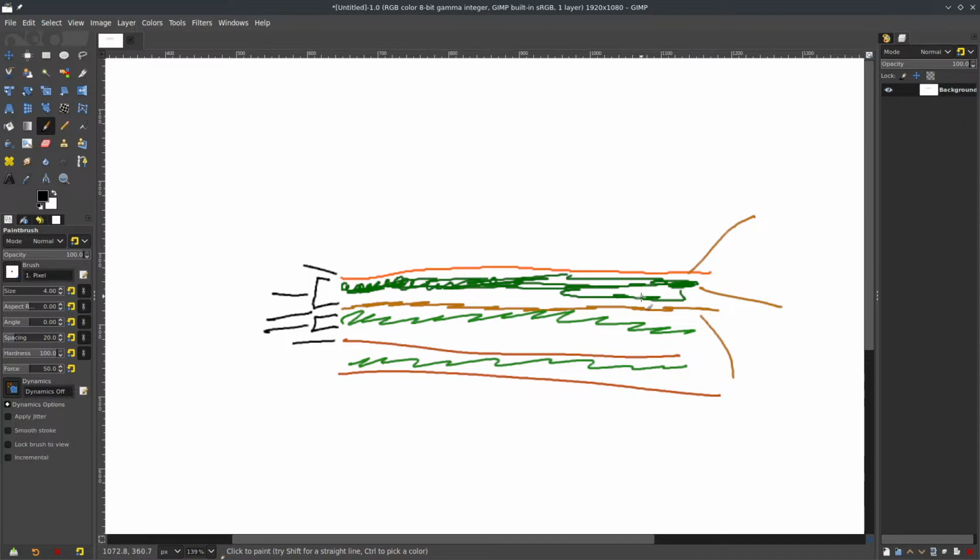Very commonly you'll have what's referred to as 2-ounce copper, which is 2 ounces weight-wise of copper per some area. And then you'll have half ounce on the inside, but there are other options besides that. That's what JLC PCB uses, and it is the most common that you'll see around.